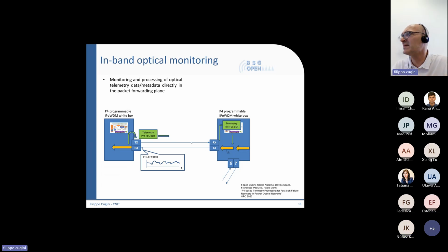So if I understand correctly, yes, for a specific transmission configuration, we will have a specific threshold. If we change the conditions, the threshold may change. It depends. But in general, with this pre-FEC bit error rate, you can define a threshold and then take actions. Consider that you cannot just move the traffic if a single sample exceeds the pre-FEC threshold.